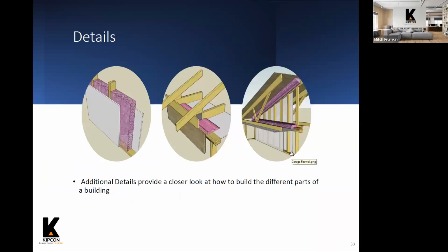So as we become more and more refined in our information in the plan set, we have looked at the title sheet, which is a very general overview of the site, orienting us to where we are on the site and maybe different types of phasing or different building types, onto more detailed information that has to do with the plan views, whether it's the roof, the floor, or the basement, and then details on building sections, sections through entire buildings or wall sections, and then even more detailed information can be found in the project details.